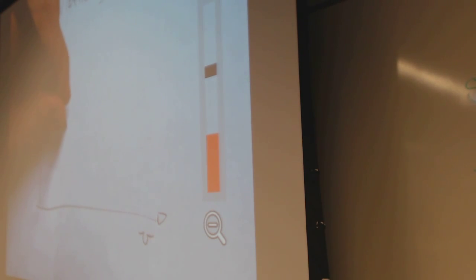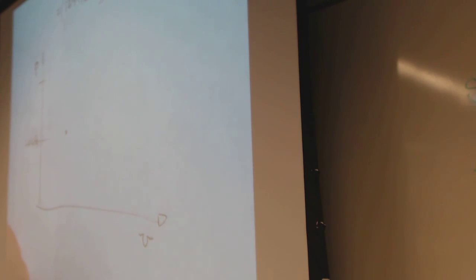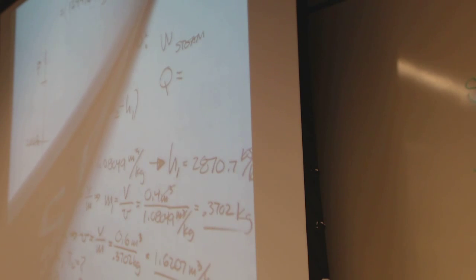So pressure 1 was 200 kilopascals. Pressure 2 was cheated. We went to 300. And this was 0.4 meters cubed per kilogram. And this was 0.6. Oh no, that's just plain old volume. No per kilogram. Started off at 0.4. It got half again bigger.